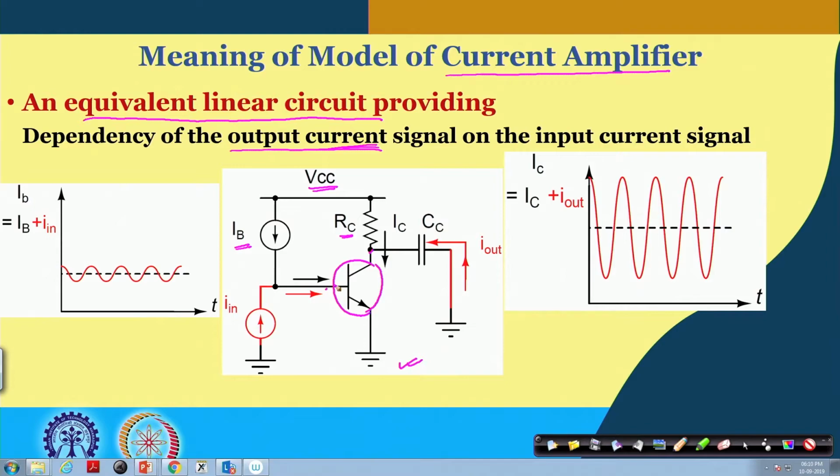base of the transistor. Either you can think of this VB setting the bias, or the DC base current, but whatever it is, it provides a bias condition. Depending on this IB and the beta of the transistor, if the device is in the active region of operation, we have a DC collector current.